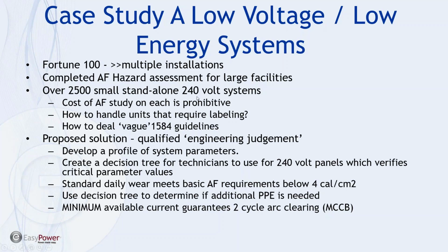Well, because these are all above 50 volts, they need to have a label on them. And unfortunately, they fall into the realm of the least accurate part of the 1584 model. And so consequently, there's kind of vague guidelines on how to deal with low energy, low voltage systems. So facilities engineering came back with a solution, effectively a study that provided a way to qualify and add additional understanding to the systems that they had to deal with. They developed a profile of the system parameters, created a decision tree, and trained the technicians to use it for all these 240 volt panels,